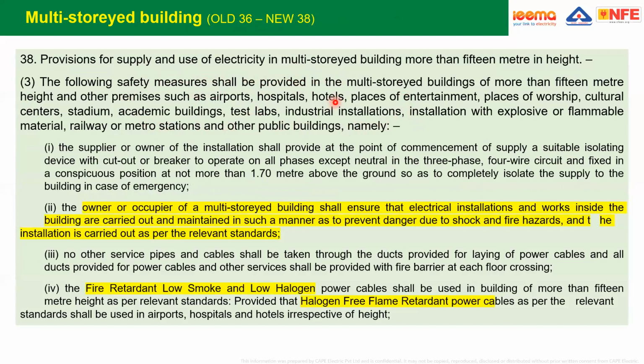It means any building more than 15 meters height and all buildings such as airports, hospital, hotel, place of entertainment, place of worship, cultural heritage, cultural center, stadium, academic building, test lab, industrial installation with explosive, flammable material, railway or metro stations and other public buildings. So all these buildings, starting from airport up to public building, irrespective of height, and all the other buildings with more than 15 meters height.